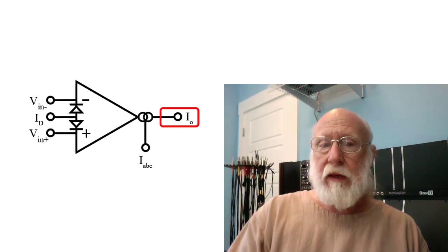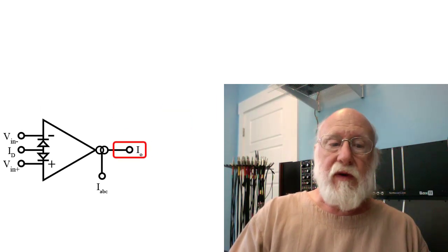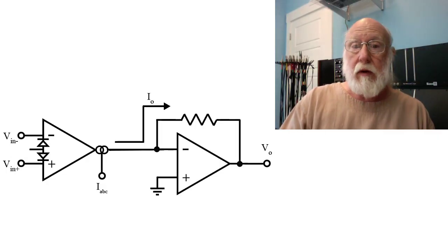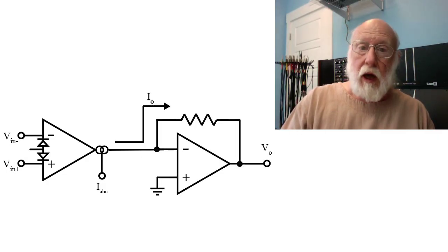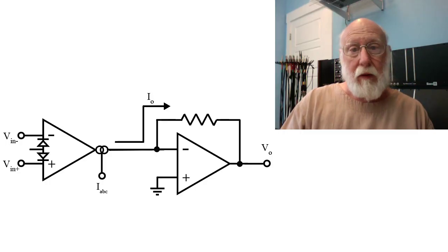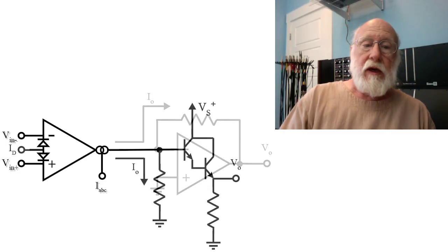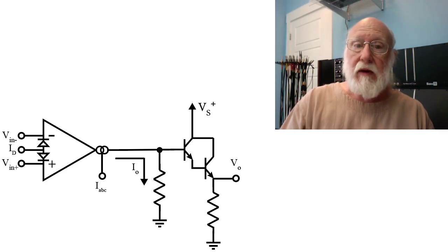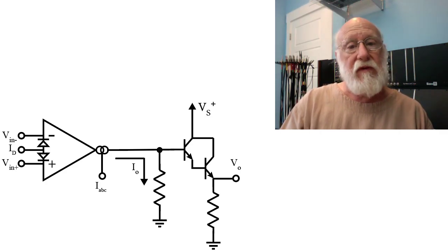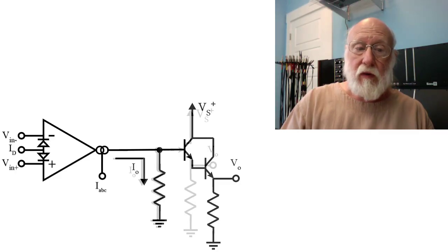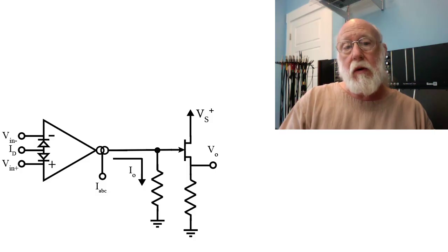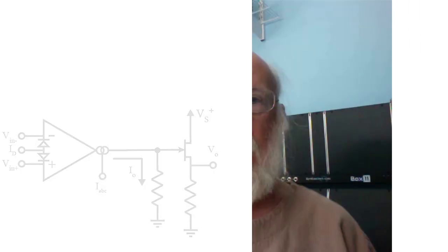We usually will want to convert that current to a voltage. You can use an operational amplifier as a current-controlled voltage source. That's one option. That requires that you add an op-amp to your circuit, of course. You can use the built-in Darlington buffers, but as mentioned in an earlier video, that will introduce about a -1 volt offset in your output voltage. You could use an FET output buffer, but again, that would also introduce a slight negative offset in your output.